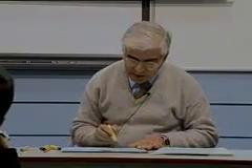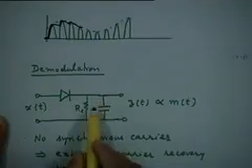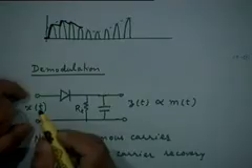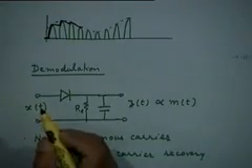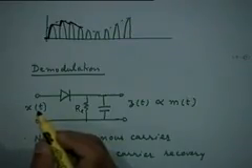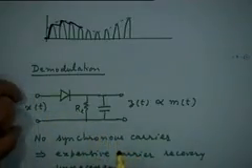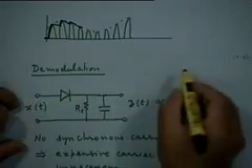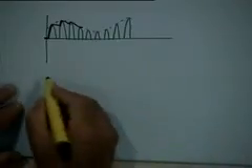Now for this to work, are there any conditions that you should satisfy? Obviously yes. Let's look at the charging path. The charging path is through, let us say, some source resistance that you might associate with the input. After all, the input is a voltage source coming from somewhere, maybe from an antenna or from some amplifier previous to the demodulator, right? So there would be a source resistance associated with the waveform x of t. Let's say the source resistance is R_s.